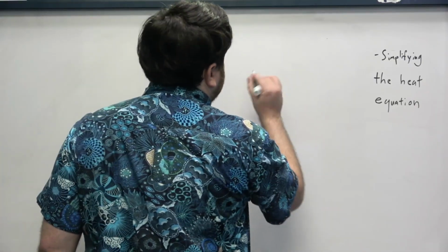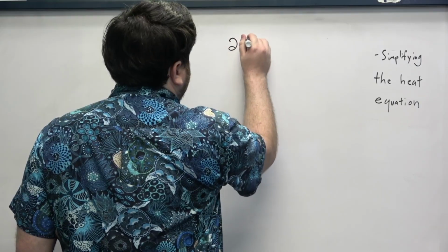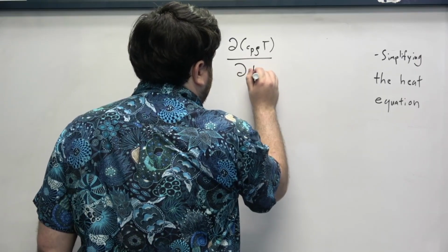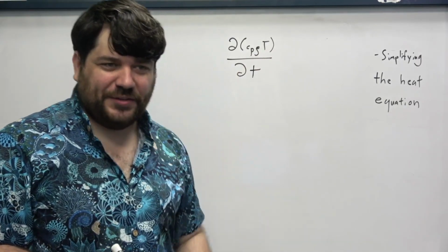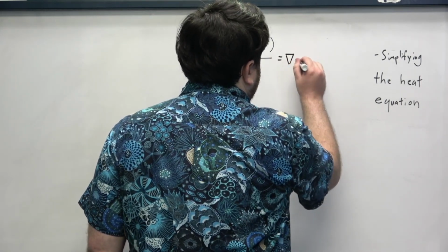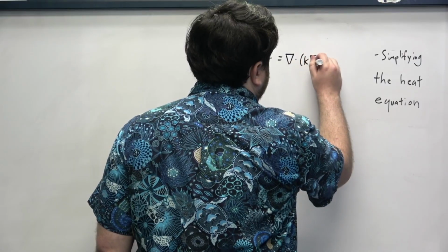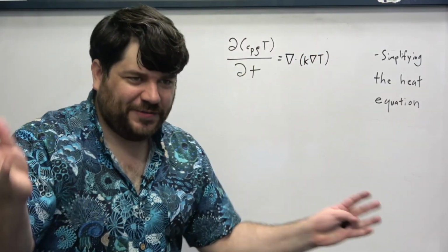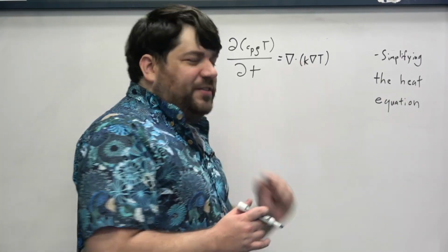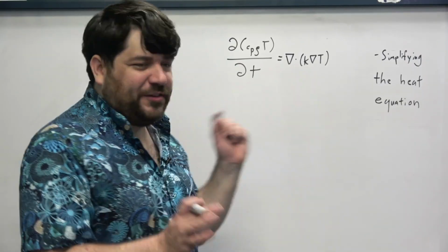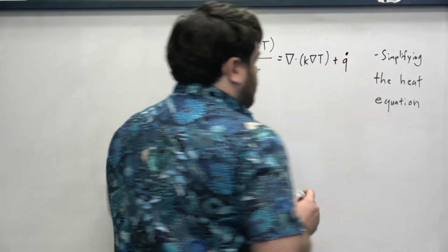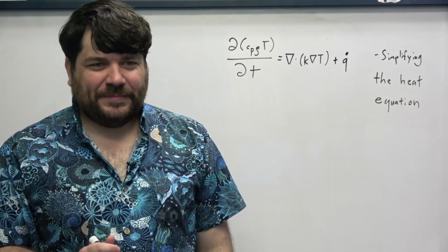So it looks like this. The general form of the heat equation is a relationship between the rate of change of the thermal energy density of a point in space with respect to time, and how that becomes connected to the divergence, which is that goofy kind of expression that's a function of rates of change of this heat flux vector, okay? Or more precisely, the negative of the heat flux vector, plus the volumetric thermal energy generation rate at a point.